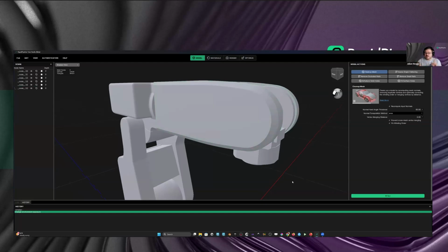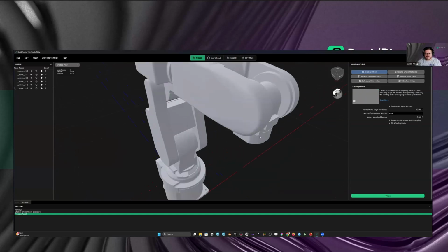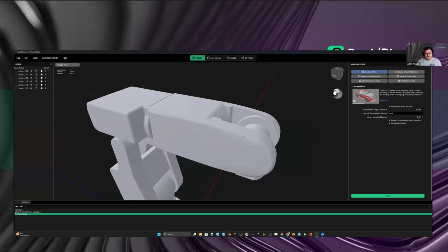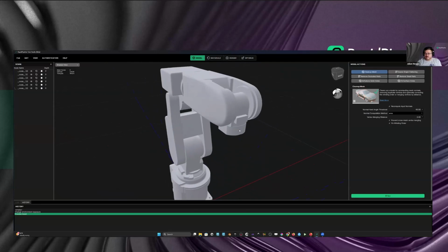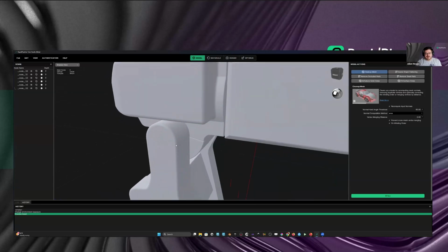And my expectation now would be, if I run this on this file, to basically get quite ugly soft edges. As you can see here, in theory, this works great if you have a really smooth, nicely tessellated model. If you know from video game production, or maybe video game is not really the right industry, but let's say for animated movies, where you have just quads and you're doing really cool subdivision workflows and stuff, they're having the soft shading, which is achieved by setting this, for example, to 60 degrees or higher. Basically, usually ends up with kind of a cool, somewhat beveled look here.